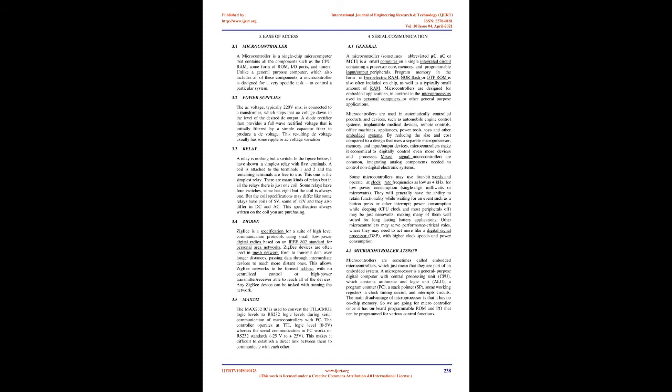By reducing the size and cost compared to a design that uses a separate microprocessor, memory, and input/output devices, microcontrollers make it economical to digitally control even more devices and processes. Mixed-signal microcontrollers are common, integrating analog components needed to control non-digital electronic systems. Some microcontrollers may use 4-bit words and operate at clock rate frequencies as low as 4 kHz, for low power consumption, single-digit milliwatts or microwatts.